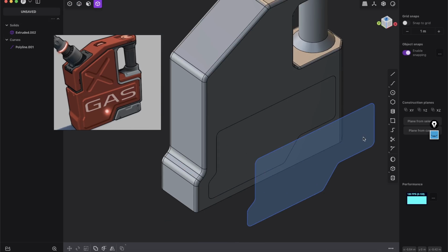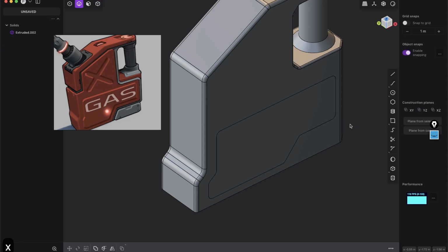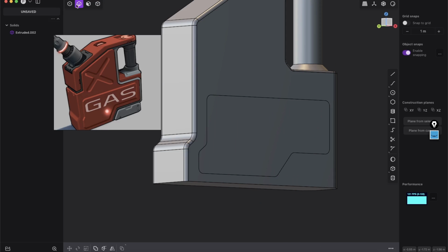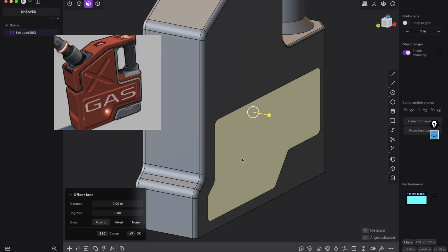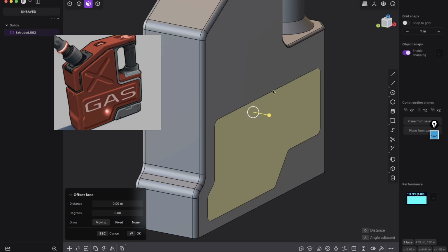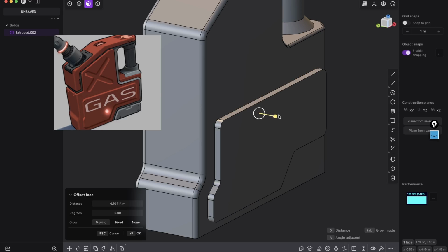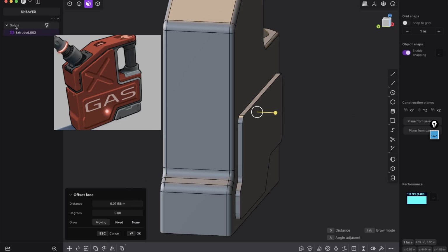But now, so press 2 and select the curve, press H to hide it, or we don't really need it, so just press X and delete it. And now you see we have this curve here on our surface. So that means if we press 3, face mode, we can select now just this face here. And if we select only this face here, we can also extrude just this face, again with this little thing here. And you see, it's still one body,